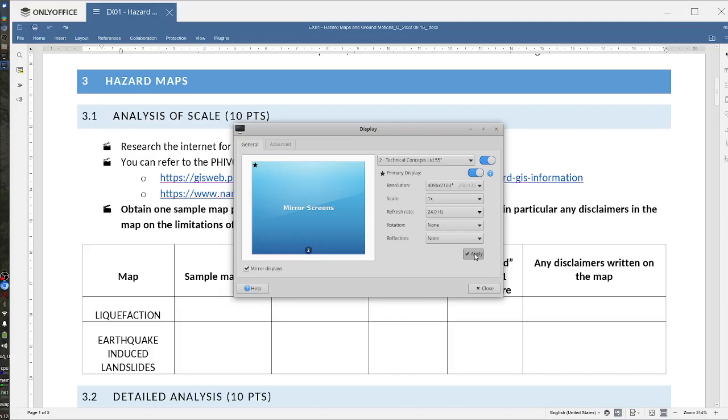I think that relates to what you asked before about the blind faults. Of course, the subsurface rupture length will always be longer than the surface rupture length. RW is rupture width, down dip rupture width. RA is the rupture area. Okay. So yeah, I'm just showing where the equation in the exercise came from.